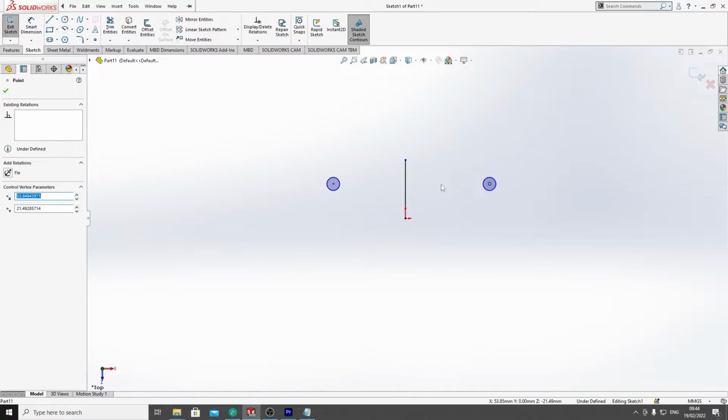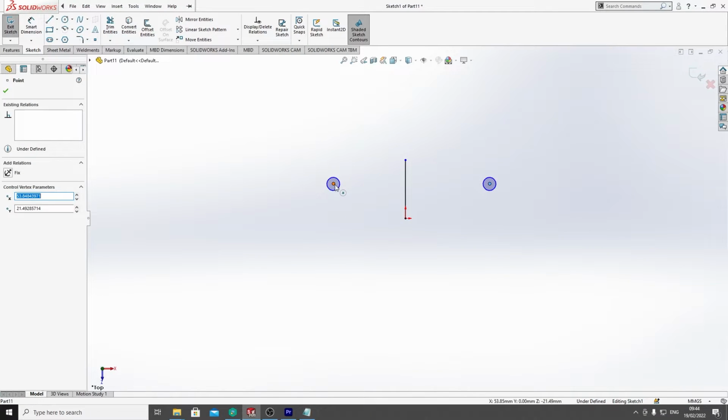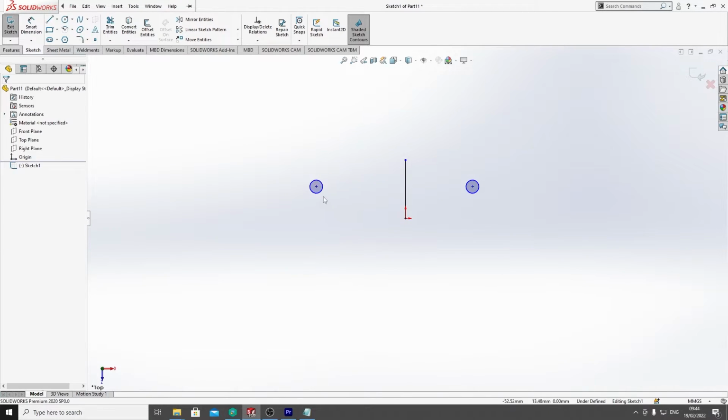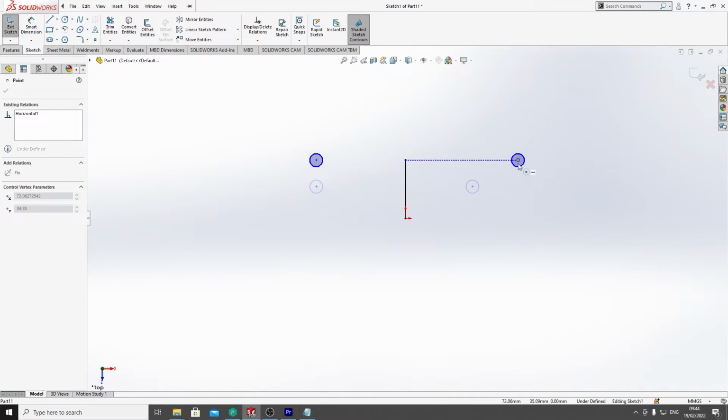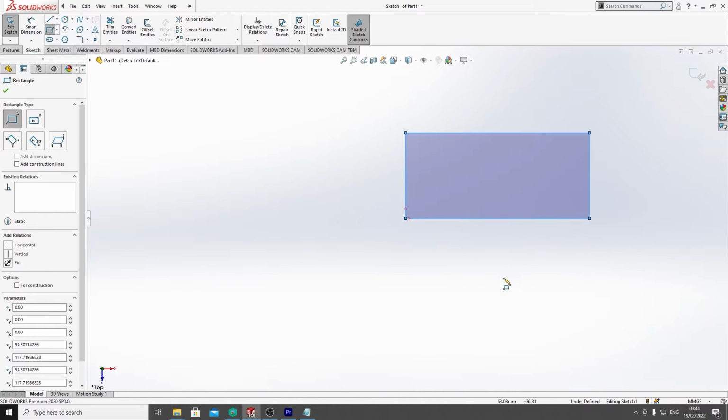So another way you can do somewhat symmetry is if you do this and this, click the origin points and then do horizontal. You're basically applying a constraint to these objects saying, no matter what happens, stay in the horizontal. So no matter how, stay in the vertical plane aligned with one another. So no matter how far you may go from the other one, they will always line up. And this is kind of like part of creating constraints within SolidWorks. So let's show how to do constraints within actual features now.